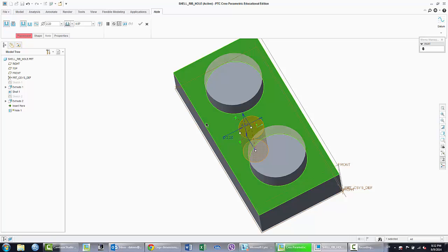And as soon as I do that, it is going to give me some suggestion how the hole is going to be looking like and where it's going to stay. And I can see these two handlebars, the green ones. They are green because they do not have references. What I need to do is define references. If I was sketching it, then I would define reference points of the edges or a circle or different features, right? The idea is same. What we need is two reference points in this case.